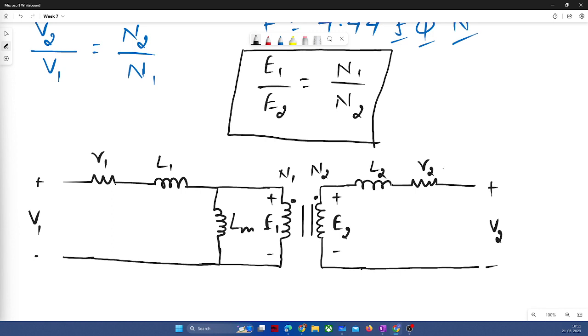To establish that much flux, how much inductance should be there? In an ideal transformer you would not see that magnetizing inductance, because we assume it is an infinitely permeable material, so we do not need a magnetizing component of current to prepare the core as a medium to couple via the flux, right?